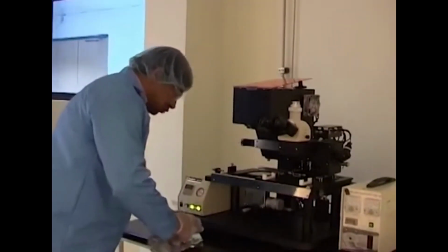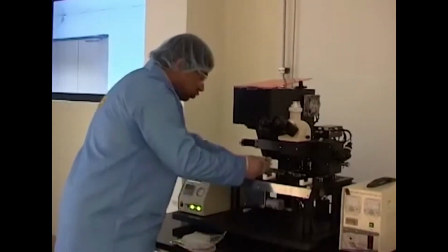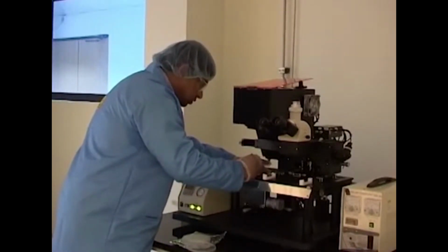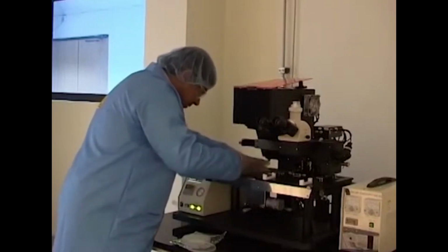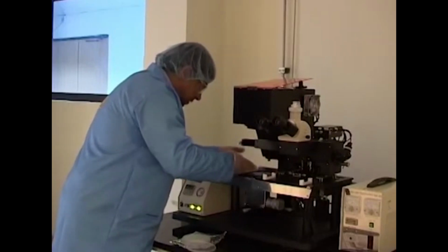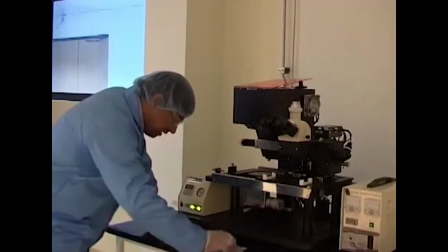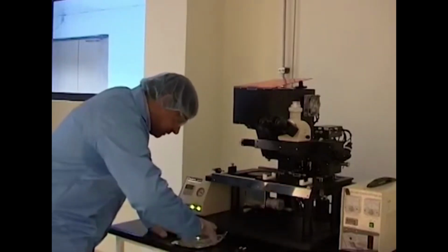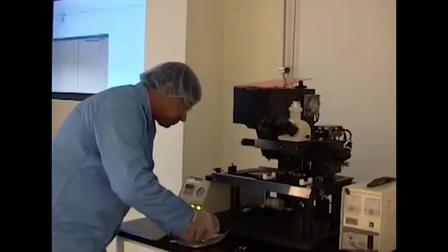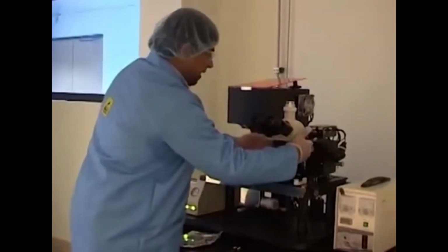We will load it back into its resting place, which is this container right here, and we will do something called post-exposure bake after this step. So slowly you have to pull out the wafer from its stage. Now it has been released, the vacuum is no longer holding it, and you slowly take it and put it back into its wafer box, cover it so that there is not much dust contamination on the surface, close it, and set the microscope back to its place.